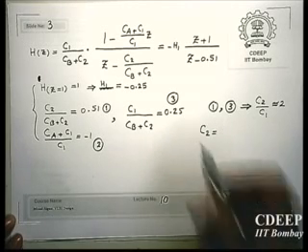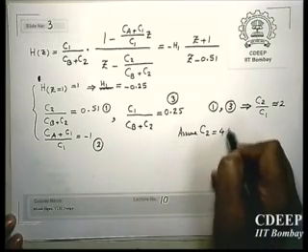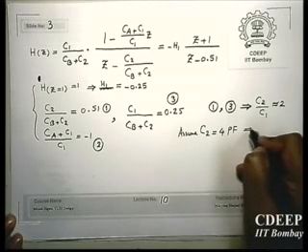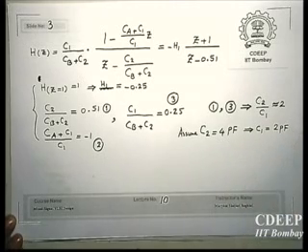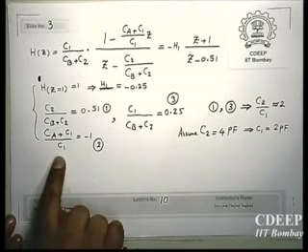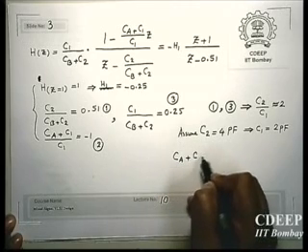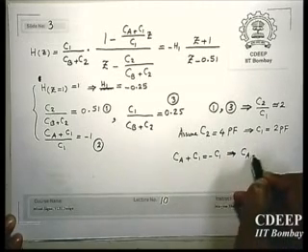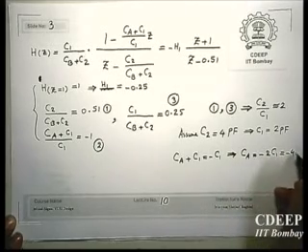Assume C2 is equal to 4 picofarad. Therefore, C1 will be 2 picofarad. So now going here, you have CA plus C1 is equal to minus C1. In other words, CA is equal to minus 2 C1, which is minus 4 picofarad.